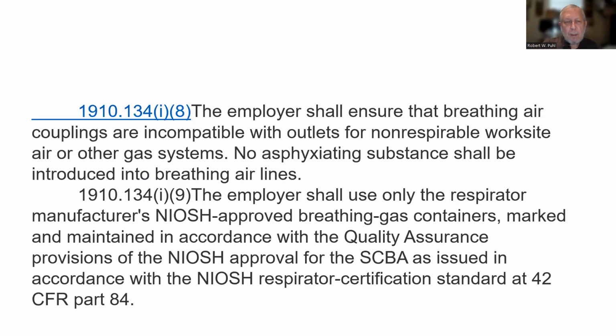The employer shall ensure that breathing air couplings are incompatible with outlets for non-respirable worksite air or other gas systems. No asphyxiating substances shall be introduced into breathing air lines. The employer shall use only the respirator manufacturer's NIOSH-approved breathing gas containers, marked and maintained in accordance with the quality assurance provisions of the NIOSH approval for the SCBA as issued in accordance with the NIOSH respirator certification standard at 42 CFR Part 84.